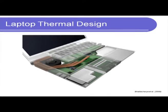The reason why we need a heat pipe is the following. We have the CPU on your motherboard, and in order to cool that CPU and dissipate the heat that is generated, we need a fan and a heat exchanger or a heat sink. However, the size of the fan and heat sink, which I am trying to show in this schematic, is much larger than what is available at the location of the CPU. We do not have the space to accommodate this fan and heatsink at the CPU location, unlike for example a desktop where you have a heatsink and a fan right on the CPU.